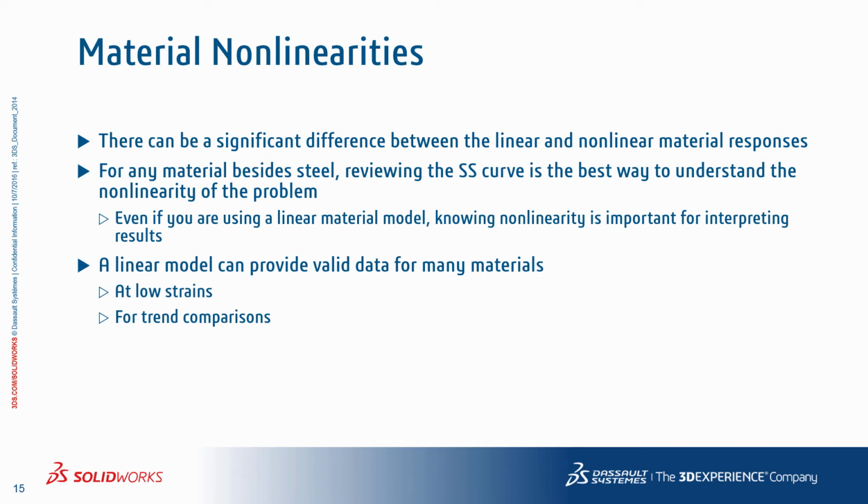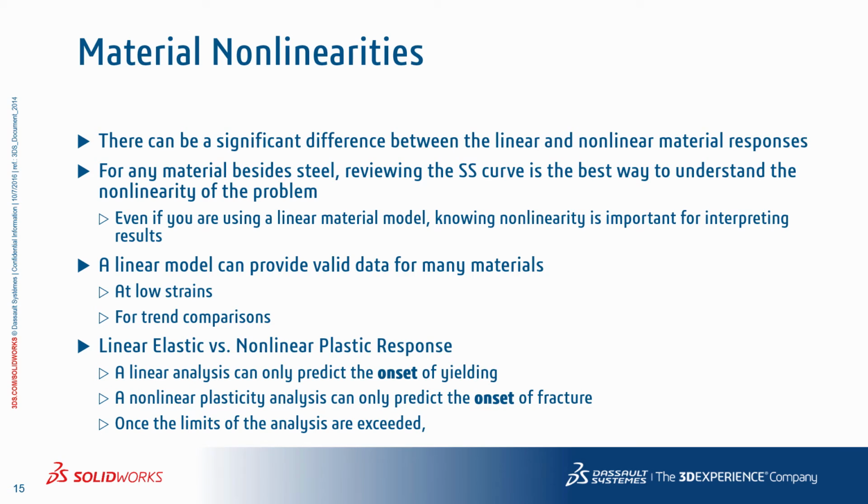A linear model can still be good enough for trend studies in a moderately nonlinear situation such as low strains, as the nonlinear response more or less would be similar to a linear response. Many components tend not to operate with stress or strain levels near the yield point. There is no need to model that plastic response, as yielding is an unacceptable performance point. Also remember that fatigue strengths for most materials are well below the yield. So if material nonlinearity and a cyclic loading is a concern, you may be better off trying to optimize a problem until it's linear.